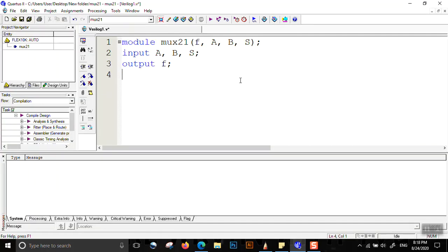So we have a NOT gate here. As we say, this NOT is a primitive of Verilog itself, or of Quartus itself. As we have already said, in the case of Verilog, at first we write the output. The general convention is that we first write the output and then the input. So our output here is Z and our input here is S.